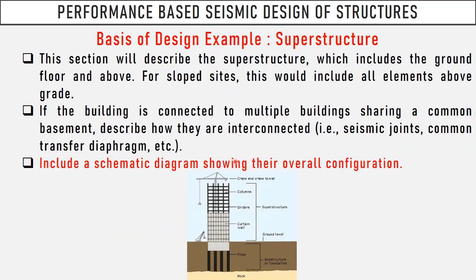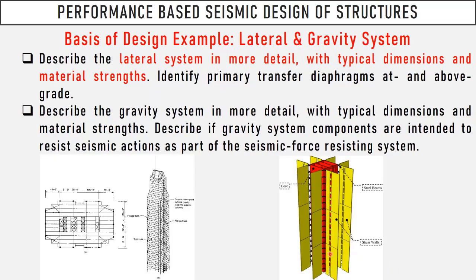You should even provide a schematic diagram of what your structure will look like, from the top to the foundation. You should even provide a detailed lateral load system and gravity system, and their connection, what their interaction is, how the connections will be, and what components you are going to use.